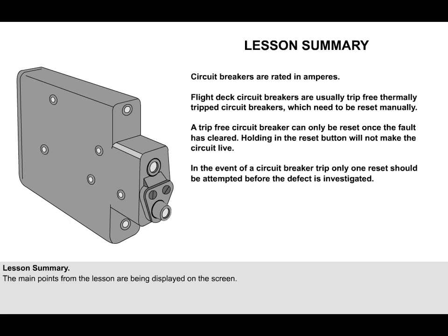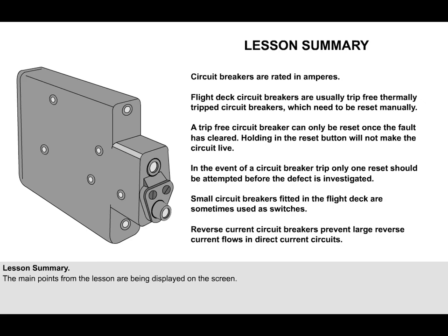In the event of a circuit breaker trip, only one reset should be attempted before the defect is investigated. Small circuit breakers fitted in the flight deck are sometimes used as switches. Reverse current circuit breakers prevent large reverse current flows in direct current circuits.